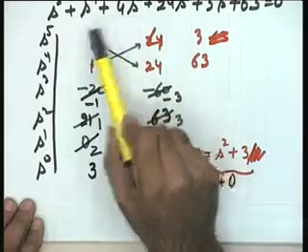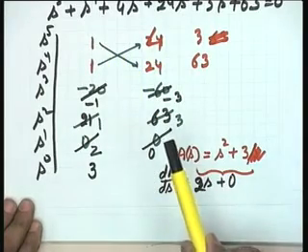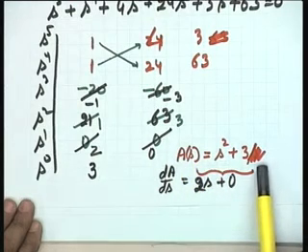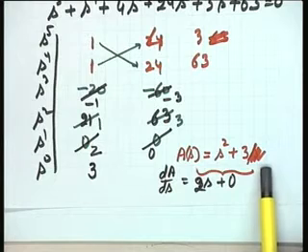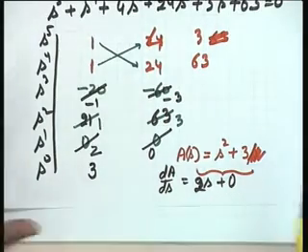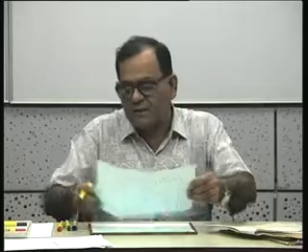So if you go back to the original polynomial, you can conclude that it has 2 roots in the right half plane, 2 roots on the imaginary axis, and obviously the balance 1 root in the left half plane, and the system is decidedly an unstable system. So in this case, you have to look at the auxiliary polynomial quickly, replace the coefficients by the coefficients of the derivative of the auxiliary polynomial, and complete the array formulation.